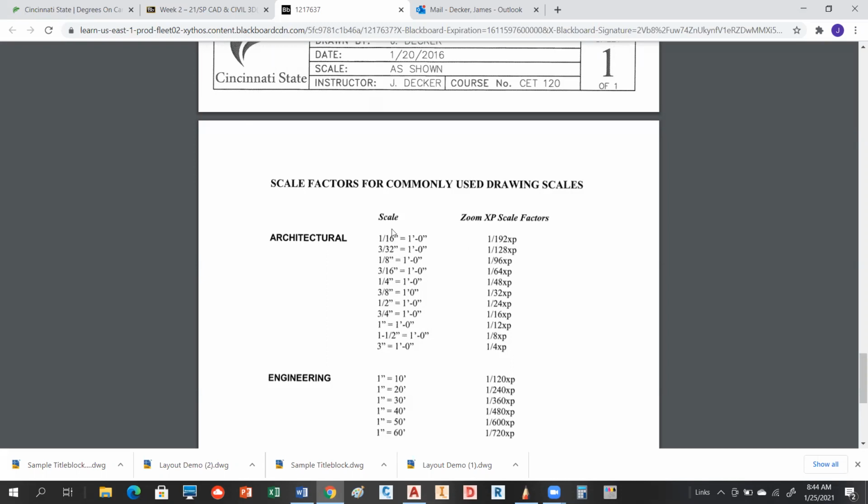The way I'm getting that is I'm setting these units to the same unit. So 1/16 is to 12, and then I'm setting it for 1 on one side and some value on the other. If I set 1/16 of an inch equal to 12 inches, I multiply both sides by 16, and I get 192 and 1.